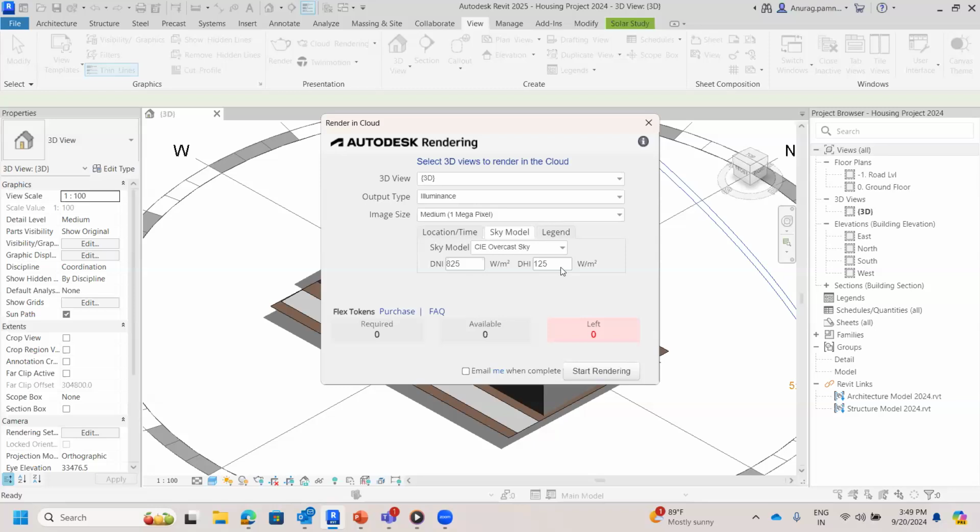These are termed as direct normal irradiance and diffused horizontal irradiance. That means how much energy is falling onto your surface, you will be able to know that. And that's particularly in a unit known as kilowatt hour per meter square. So that's the amount of energy getting onto the surface per square meter, right? So you can decide those ranges accordingly. Similarly, over here, it's divided by 1000, that's watt per meter square, without the hour involved in it.